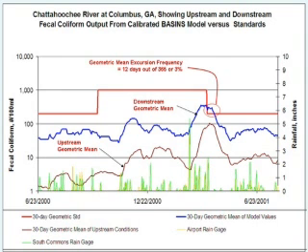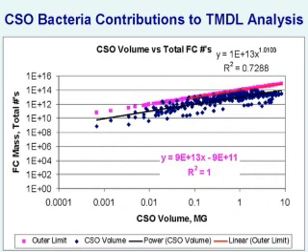This is the work done in Columbus to show that the Chattahoochee River at Columbus is in fact in compliance with water quality standards. The red line, which is a value of 200 coliforms per 100 ml as the 30-day geometric mean in the summer, goes up in the winter to 1,000. The blue line is the rolling average of the calibrated model output of bacteria in the river.